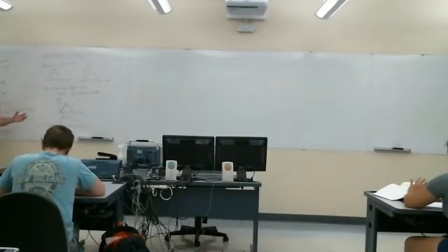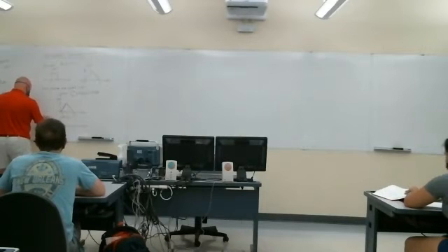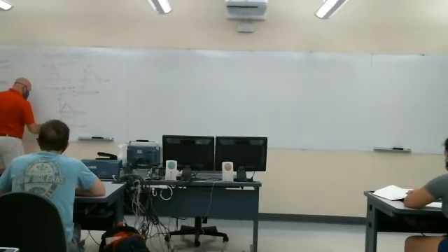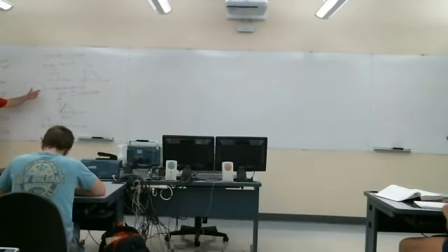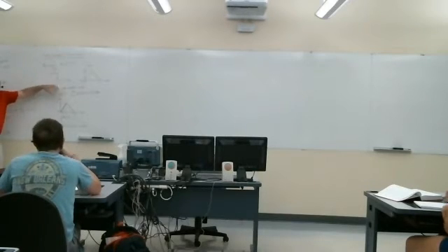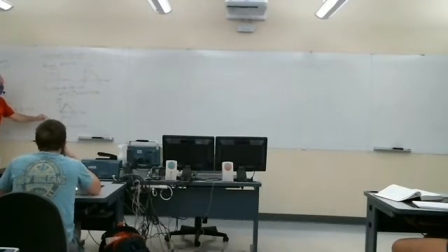So now we start typically, and in the first picture I'll draw, t is a negative value. So this is x of t minus tau. Since this thing has a width of 1, if this leading edge is at t, then this trailing edge is at t minus 1. Now you can't really tell the thing is time reversed here because it's symmetric, right? So the front edge looks just like the trailing edge. But it's time reversed, it's actually this edge that maps here, and then this edge that's at t equal 1 maps to t minus 1 here.